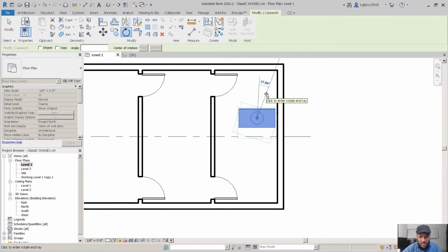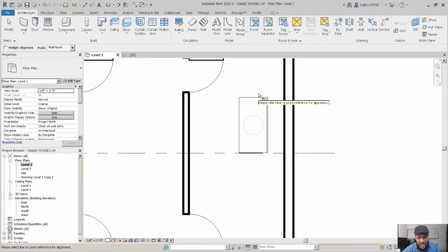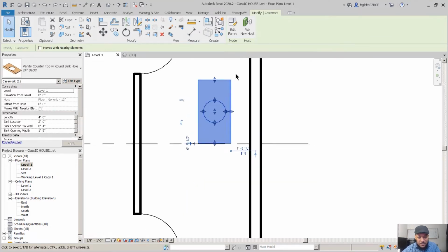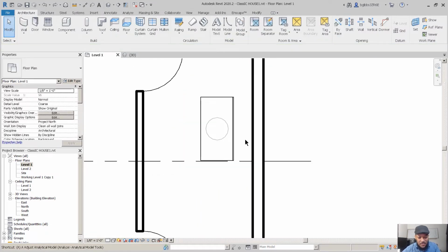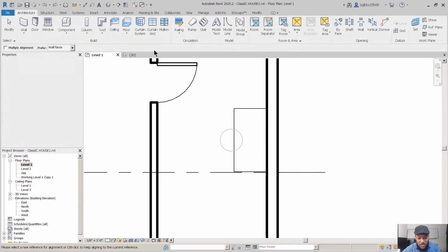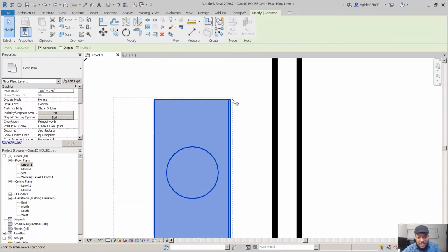And we're gonna rotate this by 90. So I just clicked R, but you could also click on this button. And I'm actually going to start using Align a lot more. Just press AL. And Align is also on the Modify tool. And we're going to undo that. So sometimes the family, things move separately. So when I pressed Align here, it only aligned part of the model. That's sort of how the family's set up. So sometimes you can use it, sometimes you can't. We're going to put this in that wall.